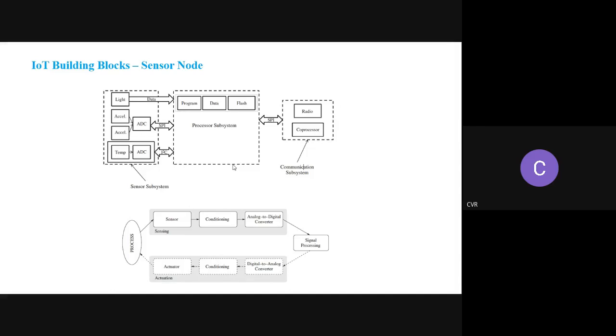For example, you have a temperature sensor in a factory, so you need not read the temperature always. You have to read periodically. That means by the time when you're not using the sensors and the respective circuit, you can switch it off. So that way it is possible. That is one of the major purposes of the processor.